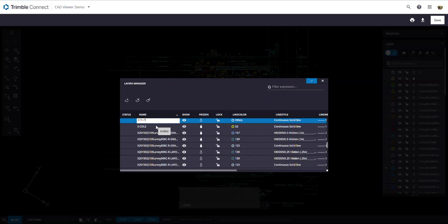And then we're going to call it property line. So we're going to change the property line in this drawing to this particular layer. And we're going to use some unique color. So we're going to use a magenta color for the property line. And then we will go ahead and create another new layer. And this one will be STK dash.